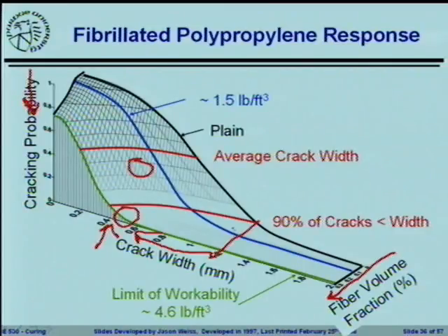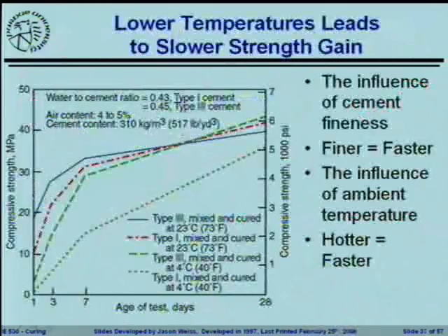The flow rate through a crack scales as the width of the crack cubed. So here, if we drop the crack width in half, we don't necessarily drop the flow rate in half. We drop the flow rate down to something like 1/8 of what it actually was. And believe it or not, we'll actually spend some time later on talking about where that number comes from. So you'll be able to prove it to all your friends, win bar bets, and all those exciting things. Anybody excited about that? One person's going to win a bar bet with that.